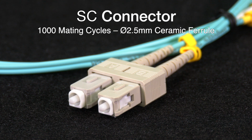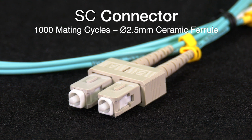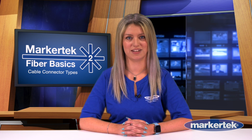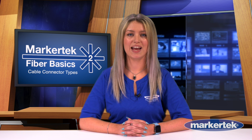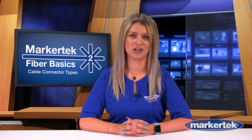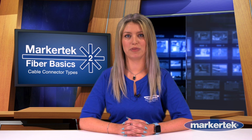Next, we have the SC connector, sometimes referred to as the square connector. It's one of the original small form factor ceramic fiber connectors. It is considered a push-pull device like the LC. Its use has dwindled in favor of the LC over time. SC connectors are commonly beige for OM1 or OM2 multimode, aqua for OM3 and OM4 multimode, or blue for single mode.